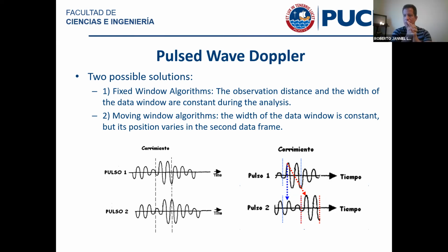It's the same thing that happened with grating lobes. And this is the nice thing, because you get to see that many of the things you have been learning over your many courses come together. Keep that in mind. So there's going to be aliasing, and you cannot measure any flow speed with pulse wave Doppler. There are limitations that we're going to clearly describe in our next lecture, because it's already 4:40.